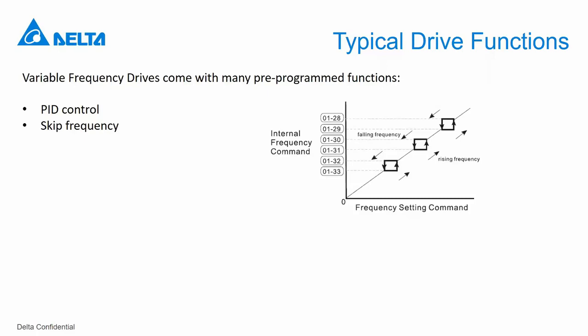And I just mentioned now for an analog input of 0 to 10 volts, but you can also do it if your input is 4 to 20 milliamps. So that would work in a similar manner. If your command is somewhere at 12 milliamps, then that can be 0 Hertz. And then when it's below 12 milliamps, then it can increase the speed in the negative direction, in the reverse direction. And when it's above 12 milliamps, it can run in forward direction.